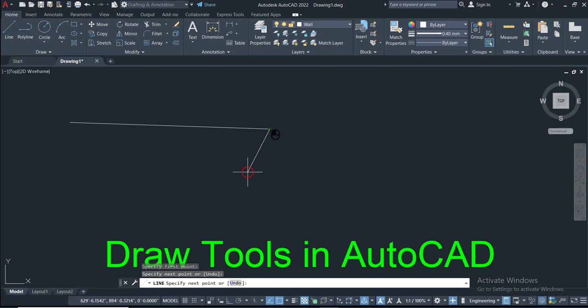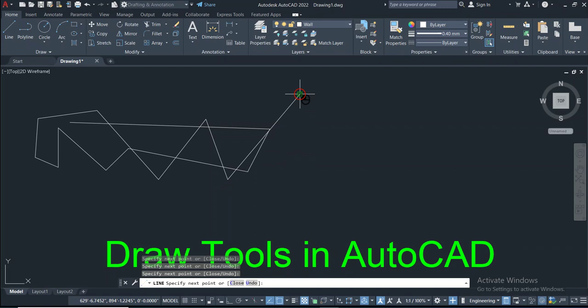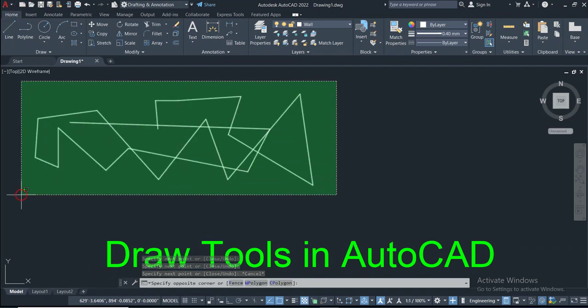So this is the next point, and then it requires you to specify the next point. Depending on the requirements, you can assign different points to the line, and the line can be drawn. So this is the first tool available in the draw tools in AutoCAD. Through this you can draw any type of line depending on your requirements.